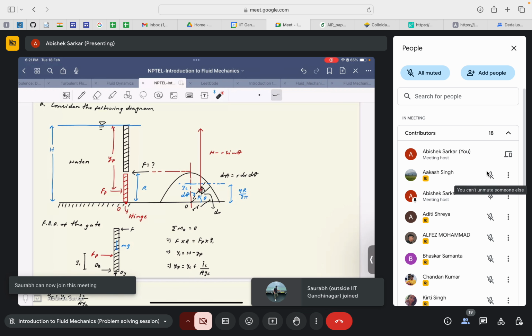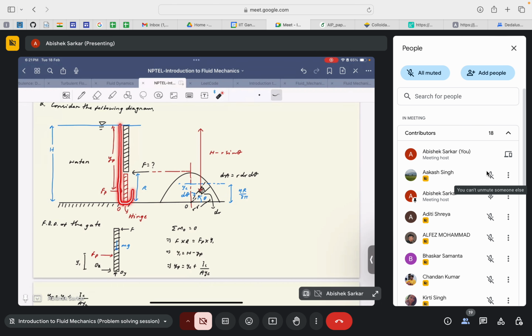So again, to reiterate, the fluid is being contained in this, but is held together by this particular geometry or design, and the lower portion of this structure is able to operate with respect to the hinge. And since it holds a fluid up to a certain depth of h, this fluid will impart pressure forces on this particular gate, which will try to open this gate. But since we want to have control, we are applying a certain force up to a point where we have to prevent this gate from opening, and once we want to open this gate, we can remove this force.